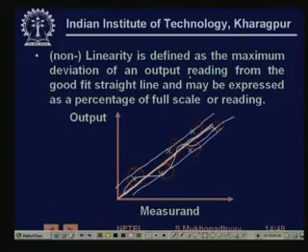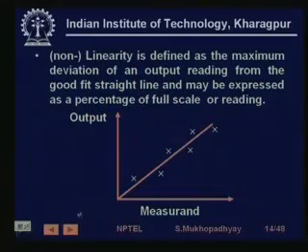So obviously you want the linearity specification to be small, so that you are telling the user that if you use that straight line characteristic, you are not going to have much error. So that it is the smallest possible, you have to take all the data and make a best fit straight line such that the sum of square of errors is the least, or something like that. So that's linearity: the deviation of the calibration data from some good straight line, which you have obtained either by data fitting, or in some cases in a different way.